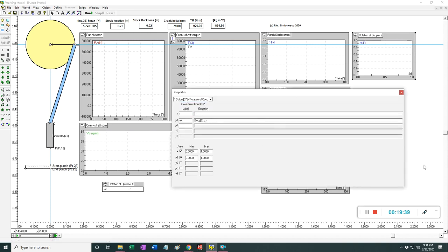So I'm going to change time to body 1 position. Of course, this is theta now, the input angle, and then the range, I changed it to 180, and then although I know it goes around 90 some amount, and then 360. These are the limits for theta, and this will be pressure angle.